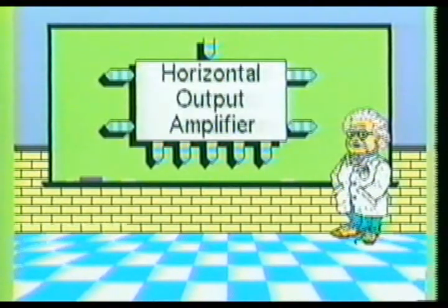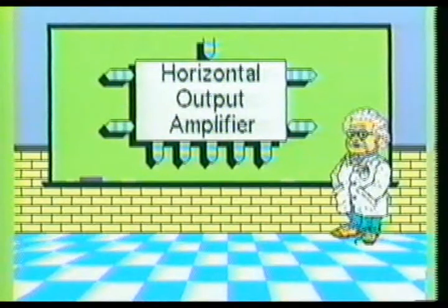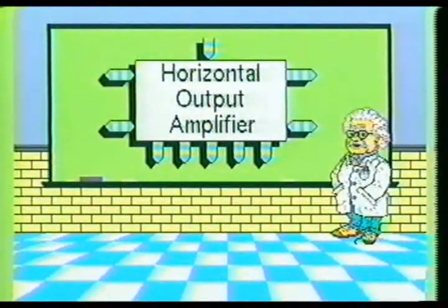The horizontal output amplifier stage is electrically connected to many of the various stages of the color television receiver. It has signals going to and from the high voltage hold down, regulator, and damper stages. It also receives a signal from the horizontal auto frequency control stage. This stage also supplies signals to the pincushion, convergence, deflection yoke, high voltage rectifier, focus rectifier, horizontal blanking amp, color killer, burst amp, and sync separator stages. This is a very crucial stage in the color television receiver.